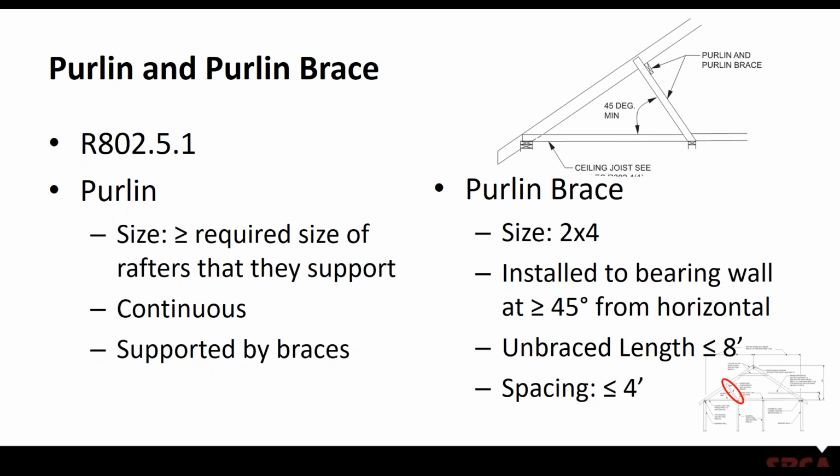So not unlike trusses, basically, where it gives you an uplift reaction, and then based on that uplift reaction, they can then decide what type of framing anchor I need to apply to the rafter. So again, similar to trusses, but a little bit different way of getting there.